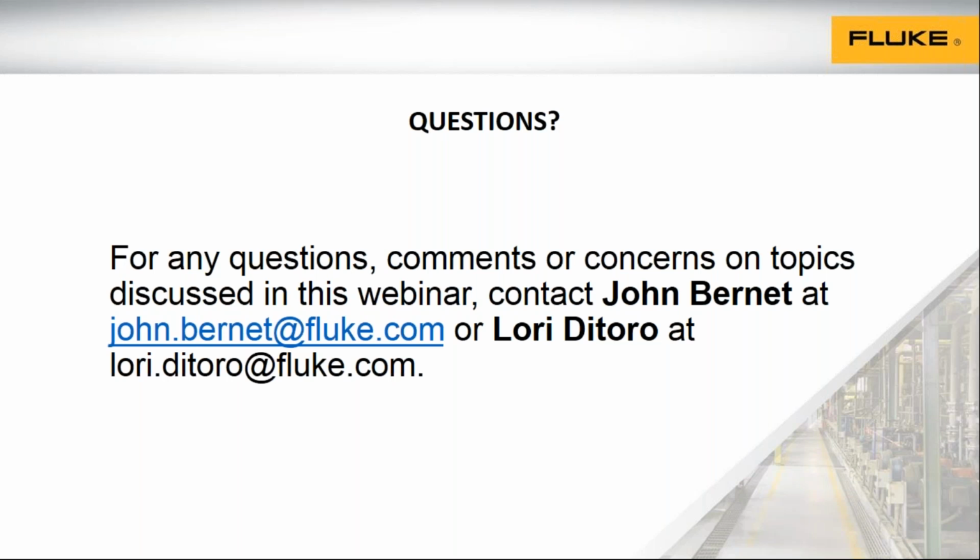But the downside is, even putting in a lot of these other factors like runtime, calendar, and history, we still find that a lot of machines fail in a random nature. I think the more factors we add and the more analysis we do, we're bringing that number down from 15%, which is really low, to a higher number. But I don't know if I've seen any studies that show that number gets better from 15% if you just do purely calendar based on rotating machinery, or if you add in runtime, or history, or other factors. I think there is still a lot of randomness. Condition-based maintenance is still the best way to know the state of a machine.